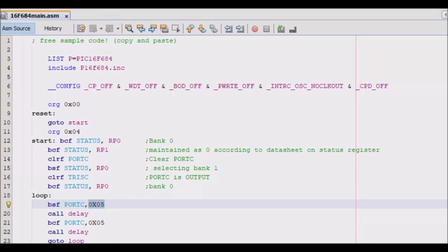I'll go a little further. The PIC18F has larger and linear memory. The PIC18F series has a larger and more linear memory space compared to the PIC16F series. This allows direct access to a much larger range of memory addresses without the need to switch banks.